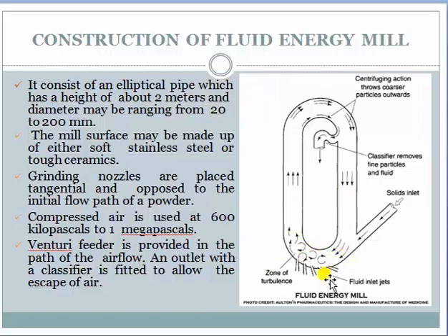Here, the compressed air is used at 600 kilopascal to 1 megapascal. A venturi feeder is provided in the path of the airflow, and the outlet of the classifier is fitted to allow the escape of air.